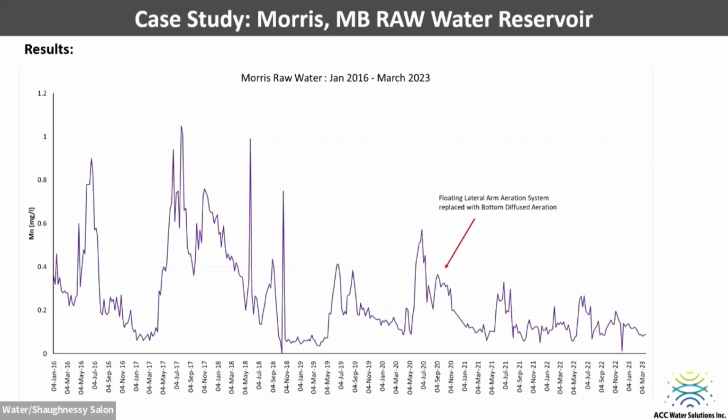Now, there are things that we want to do to improve this more over time. We would love to see them get turbo blowers in to increase the energy efficiency of their system. With the existing infrastructure, we can't. There's too many leaks in it. There's too much back pressure. It wouldn't work. If we can increase the airflow, we might be able to help with the algae more. In addition to just managing nutrients, we could possibly create some turbulent mixing and get a switch over from cyanobacteria to green algae.